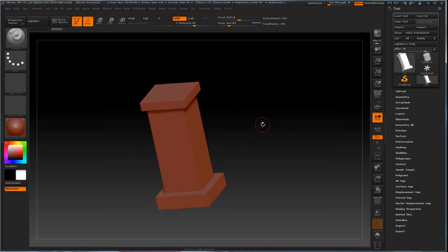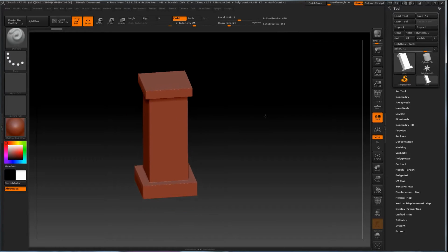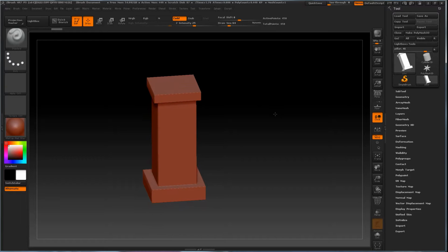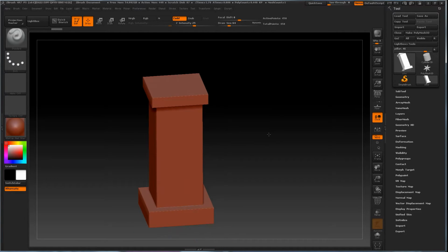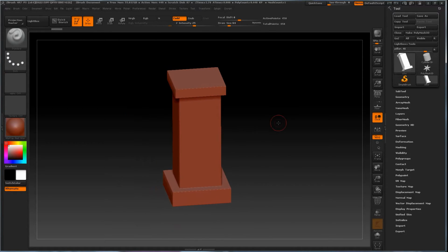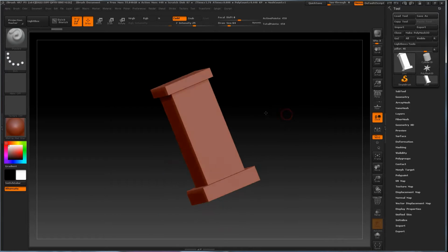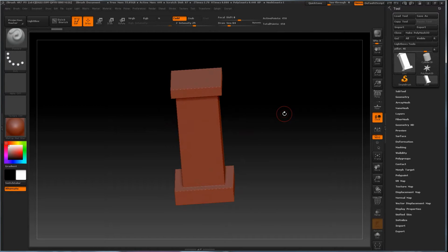Now zooming is a little more tricky. In order to zoom in this program, you don't usually use the mouse for this program, usually you would use a Cintiq or a Wacom tablet to have pressure sensitive pens to draw on the surface. In order for that to work, you would hold the Alt key like you're going to pan, and then hold the left mouse button like you're going to pan, so you essentially are panning, but don't let go of the mouse, let go of the Alt key, and it pops into zoom mode. A little confusing to get used to, but panning again is holding Alt and you can move out here, but as soon as you start moving and let go of Alt, but don't let go of the mouse, you pop into zoom. Otherwise, just left click will rotate the screen.